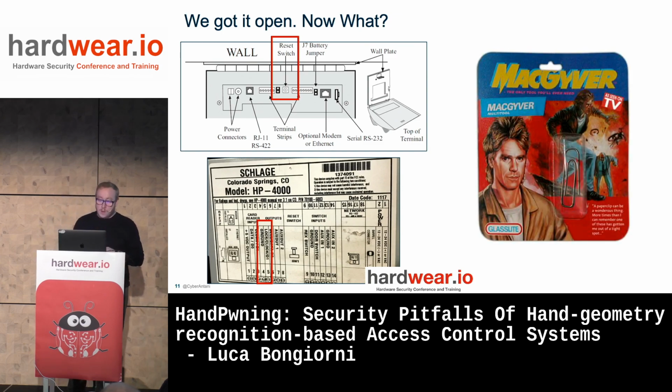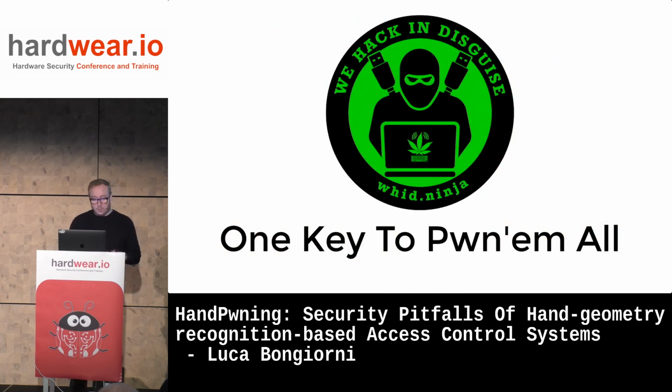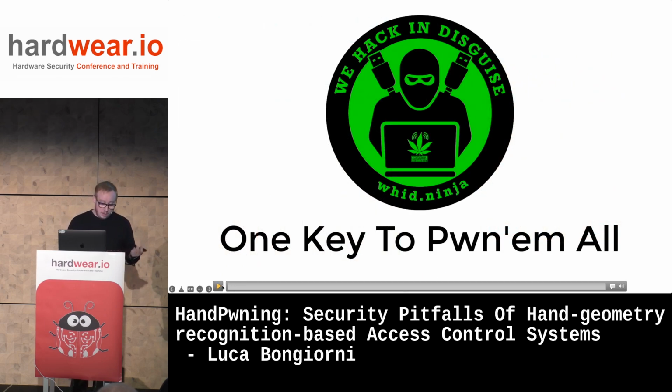There is another way, less suspicious and less noticeable to security guards or whoever owns this physical access control system: the MacGyver-style paperclip. As you can see here, you just need to be able to read English, actually. If you see here, there is one pin in the terminal called lock, clock, and D1. D1 stands for the data 1 bus of the Wiegand, because it's also using the Wiegand, the usual vulnerable protocol of physical access control systems from the 1970s. But in this case, we care about the first word, lock. So with just a paperclip and a master key that you can buy for $6, any of these devices can be popped open.